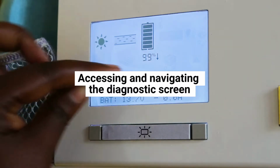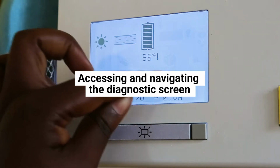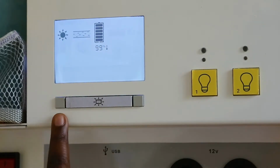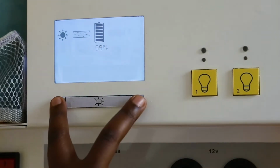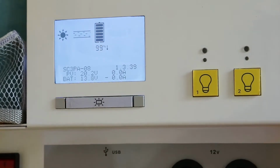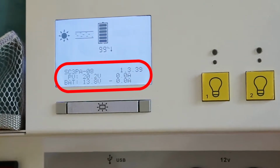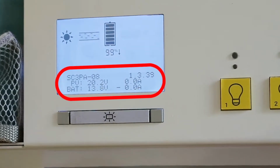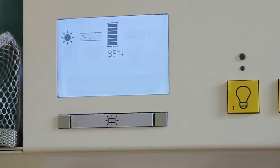Accessing and navigating the diagnostic screen. When the Solar Suitcase is on, below the display screen, push the two small buttons on each side of the backlight button at the same time. Diagnostic information appears in the message area. Don't press any button for 1 minute and the information will disappear.